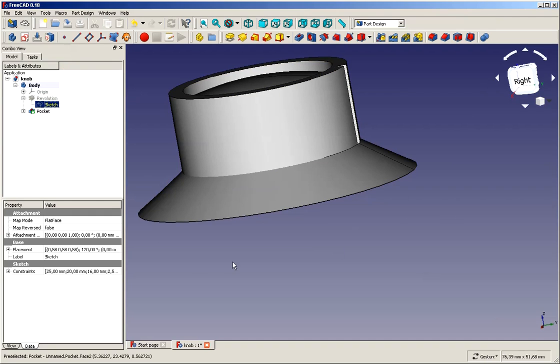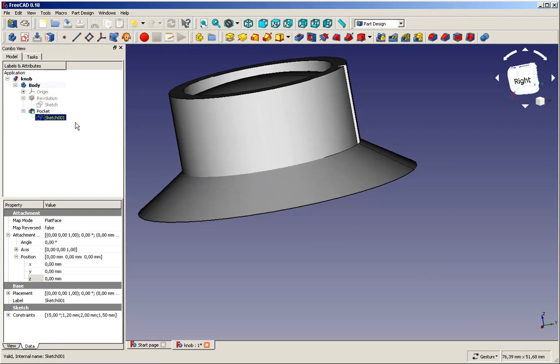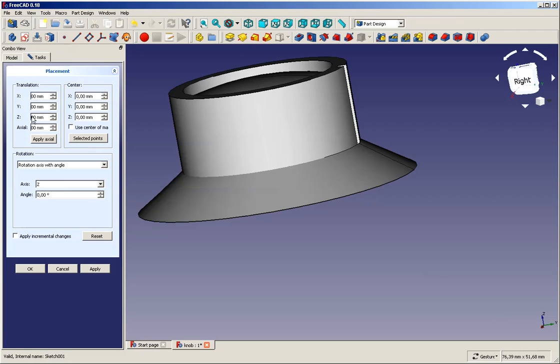We close. We select our sketch, and now comes the tricky part. You may have started to work with offsets of sketches or other things, and you may think, I choose the 3 points here, I go in there and I try to put in a constraint to our first sketch's height. That doesn't work because in this dialog the equal sign does not bring up the dialog for creating a reference.